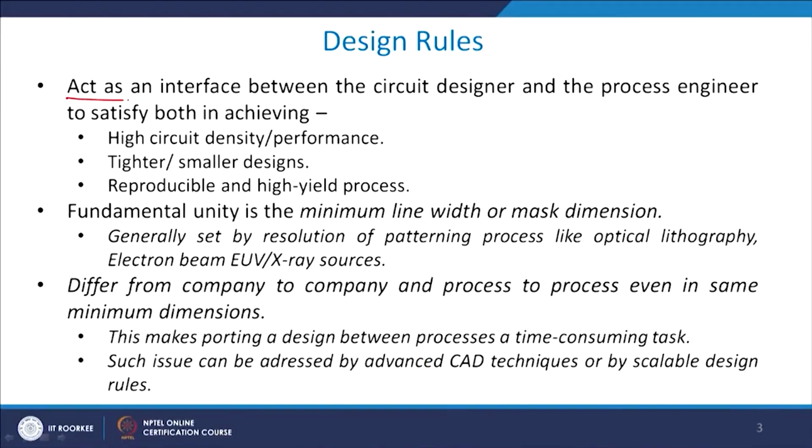So, what is a design rule? First of all, let us see that. This acts as an interface between the circuit designer and the process engineer to satisfy both in achieving high density or performance, smaller design or smaller area, and high yield processes. So, that is what I was saying in the first slide, that basically design rule checks are a common set of rules which a process engineer and a circuit designer both have to follow.